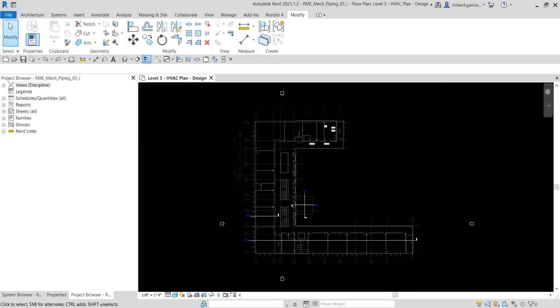In this video, we are going to add our pipe using auto layout. Again, this is a continuation of designing a mechanical piping system. Last video, we learned how to create a piping system. In this exercise, we are going to create the physical connections in the pipe system automatically using the generate layout tool, and then we are also going to manually modify the layout as required.